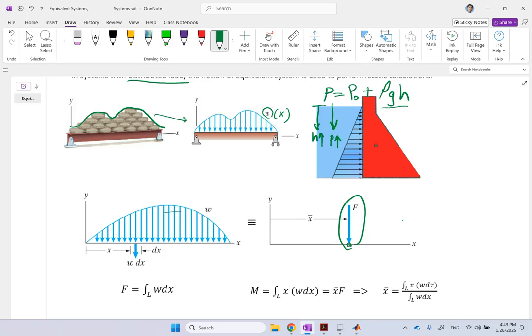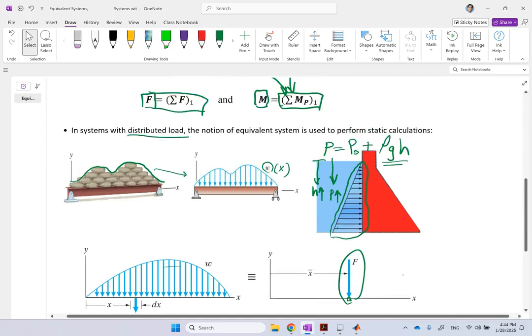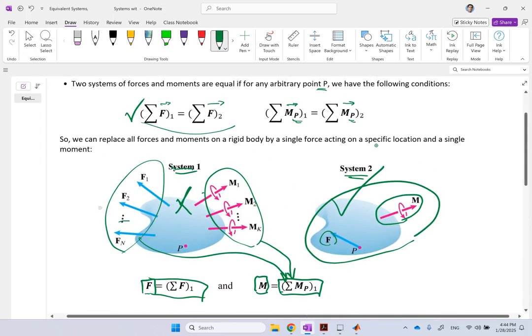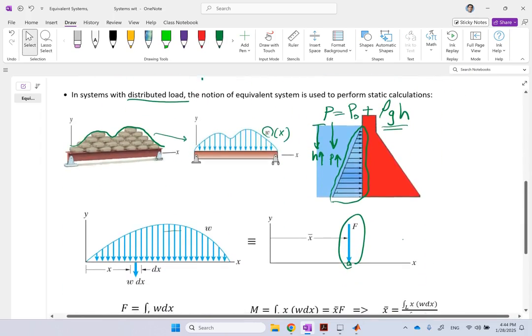And it's a linear manner with H, as you can see here. So if you look at the force on this vertical wall of the dam, it's a distributed load and it's linearly increasing. So they're all over the place, okay? Now, clearly you can consider this distributed load like a ton of individual loads. In theory, infinitely many of these individual loads, if you put them right next to each other, you can say this is a distributed load.